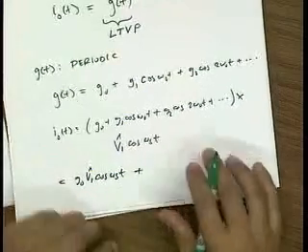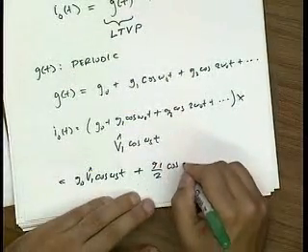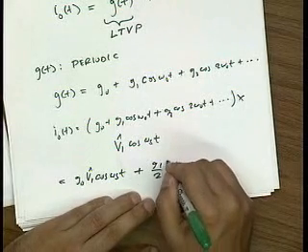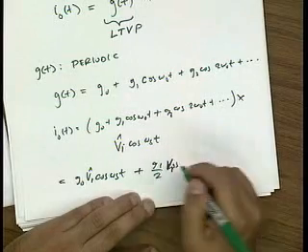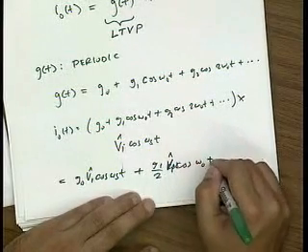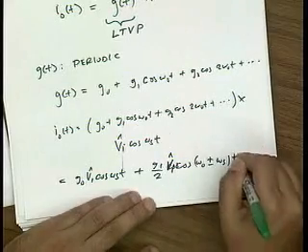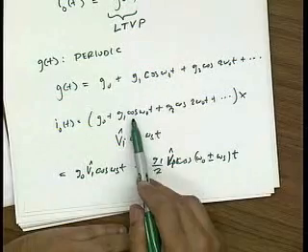That's just the linear output. And then G1 over 2 times V input, let me call this V input, times cosine of omega naught plus or minus omega s t. So that's basically frequency modulation by the cosine term.